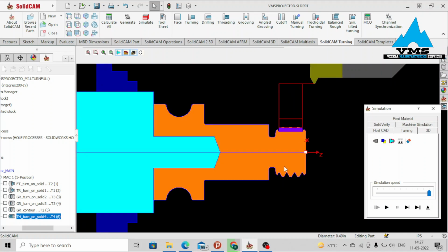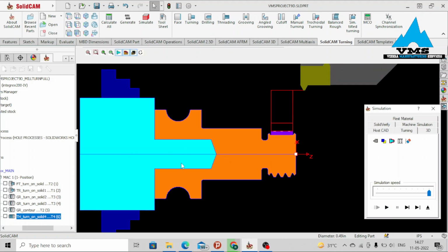We are actually done with the main spindle, right? We cannot actually machine this hole. If any attempt is made to machine this hole, even by using Mark II right now, there's going to be a collision with the jaw. So what we have to do is transfer the part. That is, we have to rotate the part.